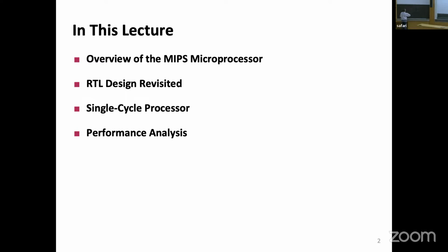On the other hand, we were talking about data path circuits where the data comes out of here, gets modified over the combinational logic, and then gets processed. In data paths, the data moves in this way, and then we have a bunch of control signals. This is the way data goes. Then there are decisions being made at every step of the way to differentiate: am I adding, am I subtracting, am I doing this? So there would be a control part that tells the data part how the data should be manipulated. Usually here, there would be a finite state machine sort of thing that determines what the control signals will be for every step of the way. These things will usually also get some inputs from somewhere or from the present state and tell you what we are going to do. So this is what we will be doing in the end.